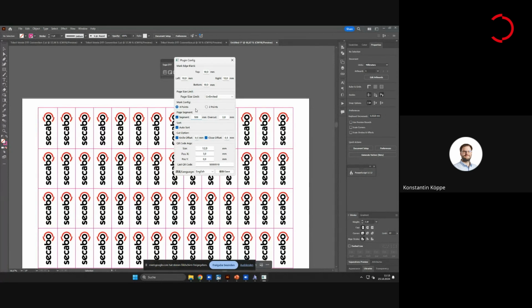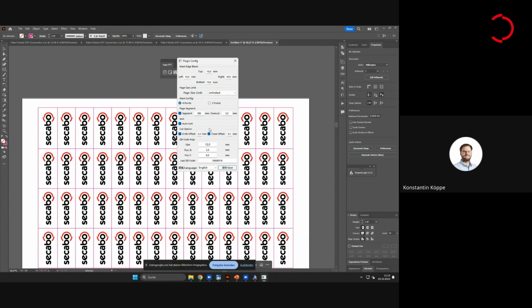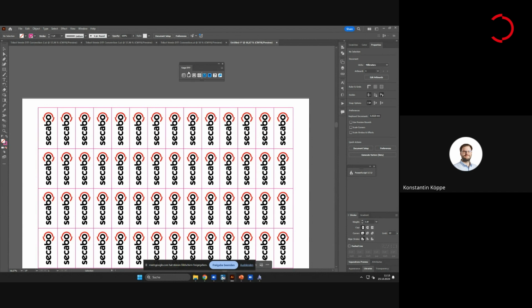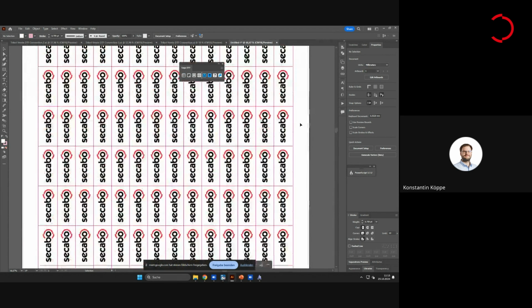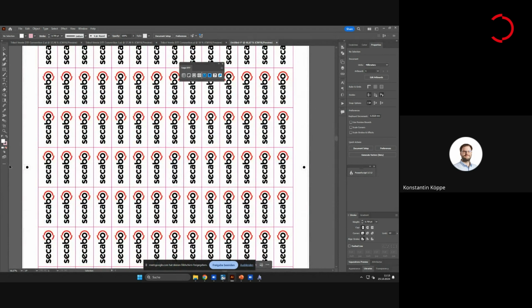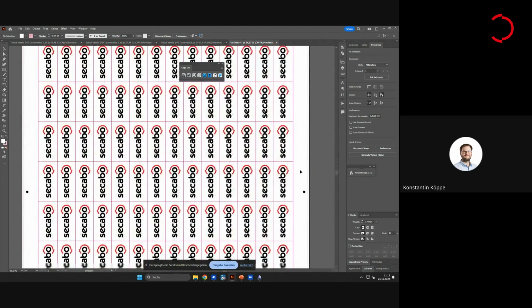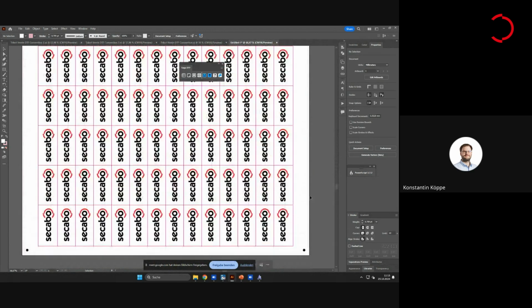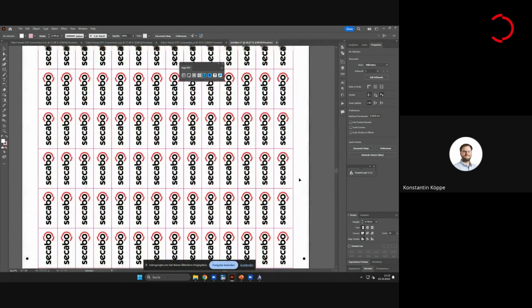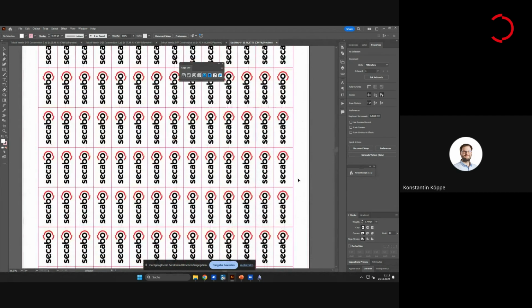And last but not least, on the lower half of this configuration dialog, we have some knife settings like the blade offset and the close offset. Just going to go ahead and save them. With the first 2 options of the plugin, we can automatically add the mark points. If we scroll down now, we can also see that the plugin took care of generating the intermediate mark points automatically at the specified intervals. So in our case, we should have a pair of marks every 50 centimeters.